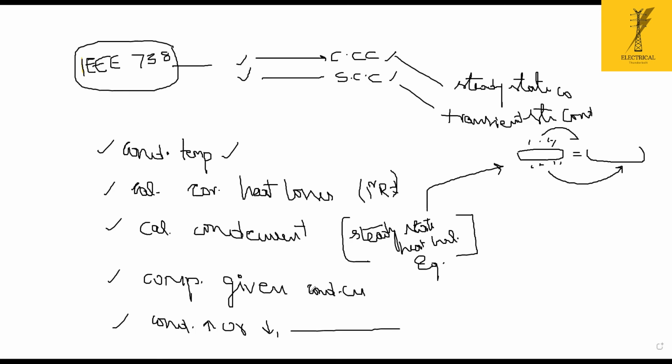If you take that and apply it in your substation, and this substation is located in the northern hemisphere and the temperature is less, and the wind speed and wind direction are good, then obviously those will act as cooling agents for your conductor. So the conductor can carry more than the given conductor current, given the temperature you are looking at.